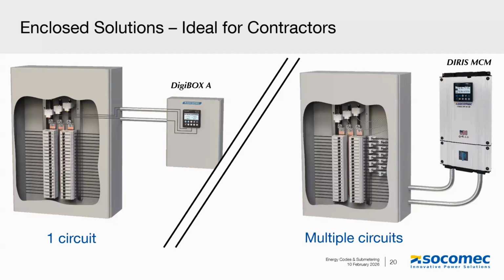So the Digibox A, and then the Dirus MCM, which is really great for high density metering when you have panels with multiple circuits, whether it's a switchboard or a panel board. All that matters is the CT, the current sensor that you select to interface with the meter. The Dirus MCM is very cost effective for monitoring multiple circuits. So in example number two, when you have multiple loads within the same panel, that's really a great and cost effective solution.